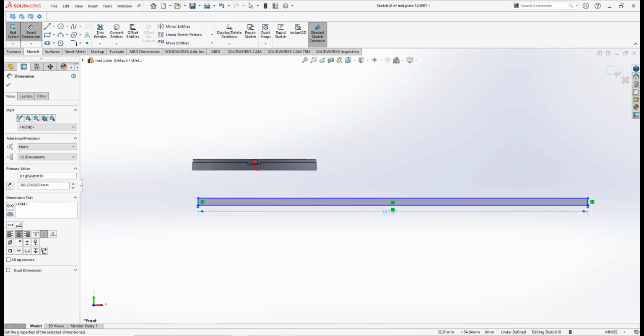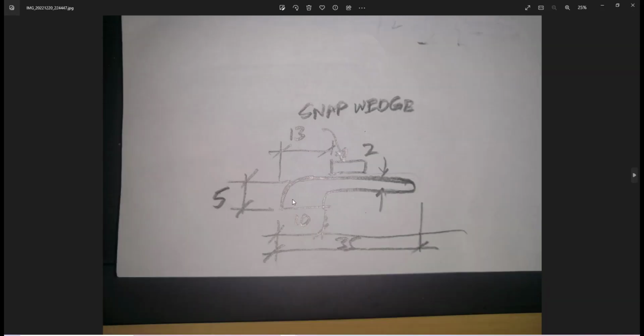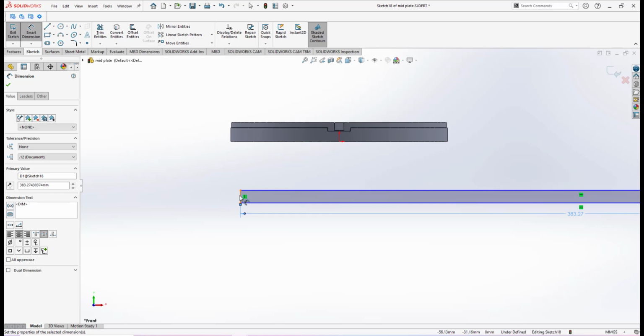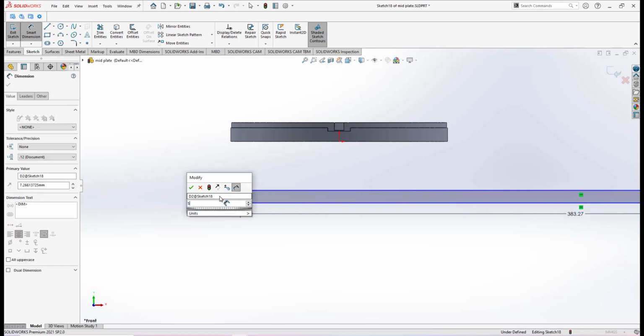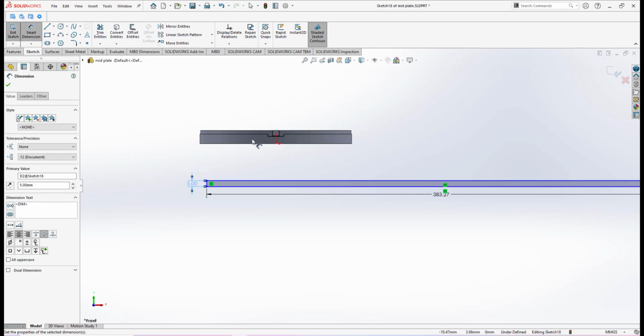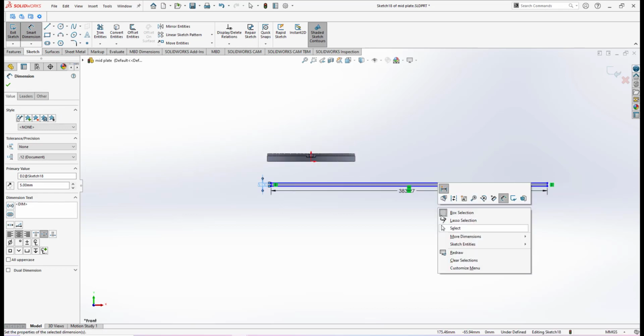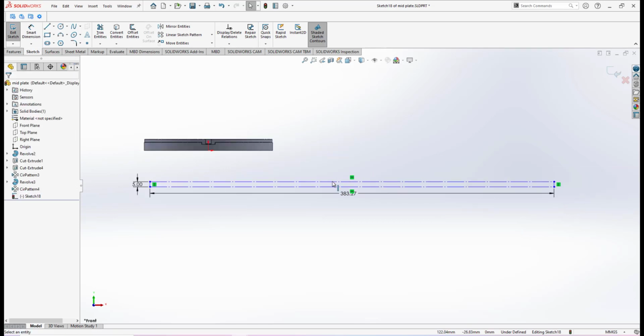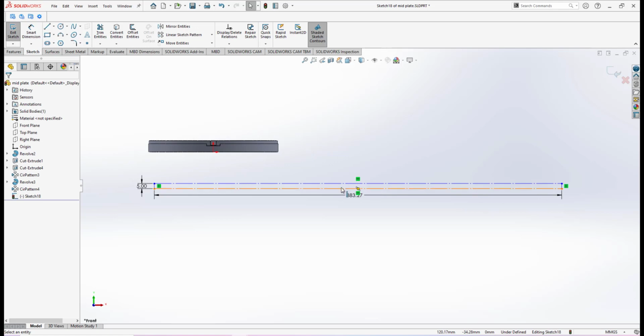Also, if you look again, the height of the sketch profile is 5, so the height of our rectangle is 5 units. So this will be the boundary for me to wrap around this cylindrical surface. I need to convert all these lines into construction geometry, because that will be our boundary. Another thing to do is to position this wrap.